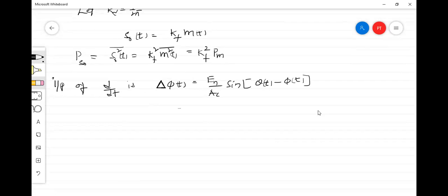Instead of finding directly the output of the differentiator from this input, let us find its noise power spectral density here itself. Once its power spectral density is found, by using the transfer function of the differentiator we can find its output noise power spectral density. From that, we can calculate the noise power easily. First, let me simplify this.